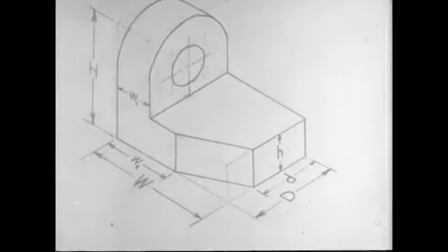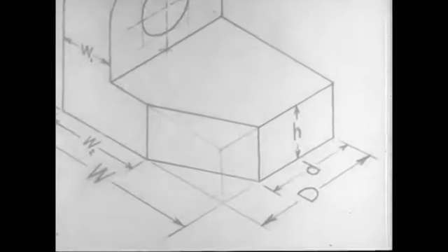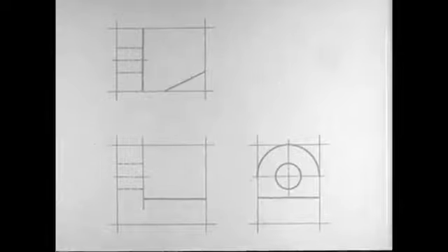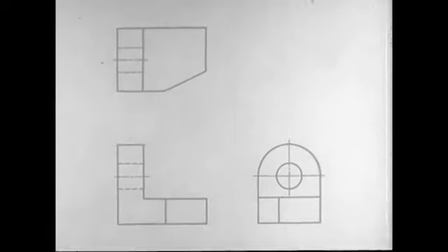From specifications, find out the width and the depth where the corner is cut off. Locate the cut off corner on the top view and project it to the front view. Measure this edge of the object on the top view and transfer this distance to the side view to show its depth there. When you have finished construction, strengthen the outlines of all the views.